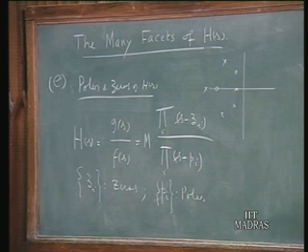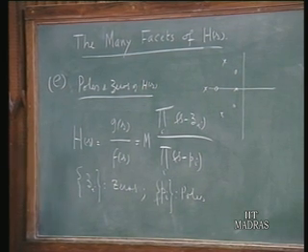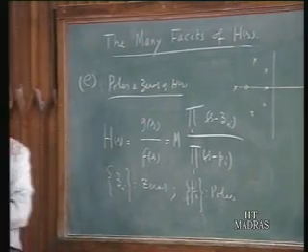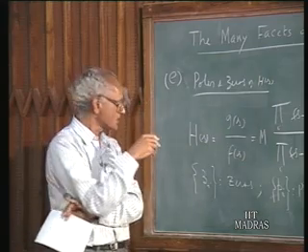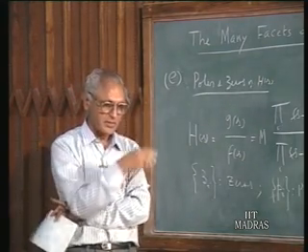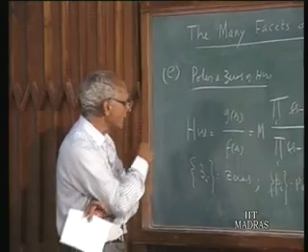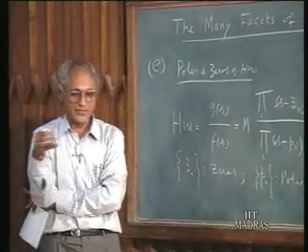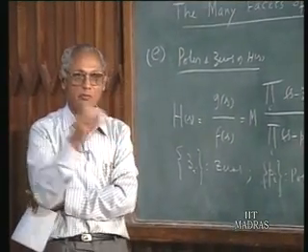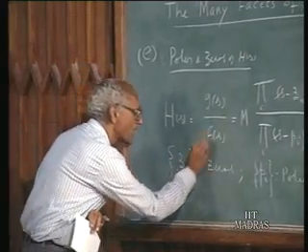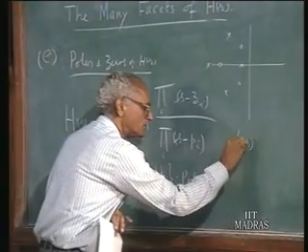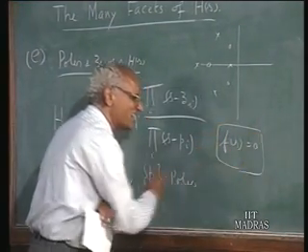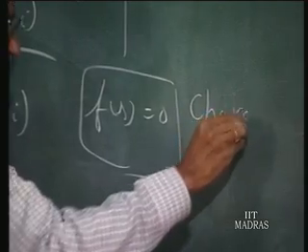Now, an important factor that one would notice in solving a system is, suppose you have different types of outputs that you are looking for, and naturally you have different system functions relating the different outputs to the corresponding input. It turns out that suppose you have H1(s), H2(s), H3(s), depending upon the y's that you are talking about, y1, y2, y3, all of them have the same F(s) in the denominator. So F(s) equals 0 is what is called the characteristic equation of the system.